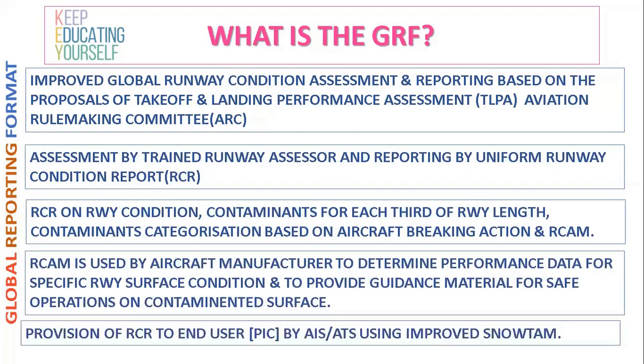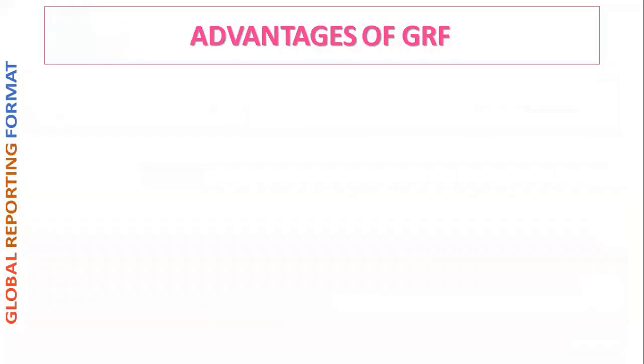The runway condition report is provided to the end user, which is of course the pilot in command, by the aeronautical information service or air traffic service using improved SNOWTAM. With this, we have some idea that runway assessment procedures have been developed and standard global reporting formats will now be used. The SNOWTAM format is also changed, or we can better say the SNOWTAM format is improved.